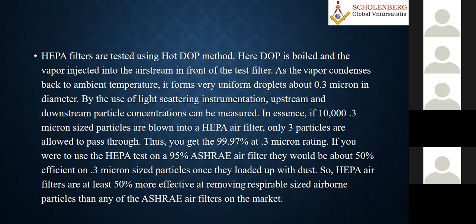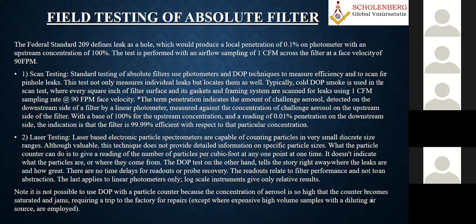If you were to use a HEPA filter tested at 95% efficiency as an air filter, it would be about 50% efficient on 0.3 micron size particles once loaded up with dust. So HEPA air filters are at least 50% more effective at removing respirable sized airborne particles than any of the air filters on the market. So that's what we always insist for: the ASHRAE test certification is a must.